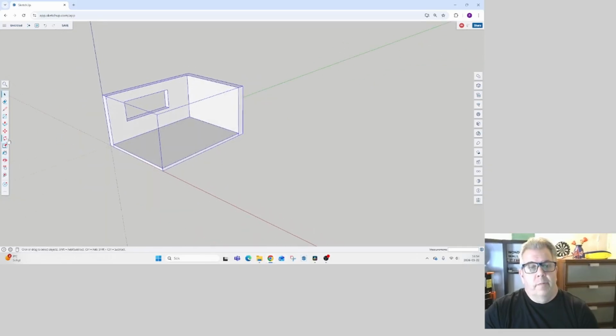And now I'm going to make the table for the room. And I'm going to do it outside of this geometry at the side. So I use the rectangle, and again I can just draw out a little rectangle, it doesn't matter, and then I can do the dimensions 1000 by 750 and enter.